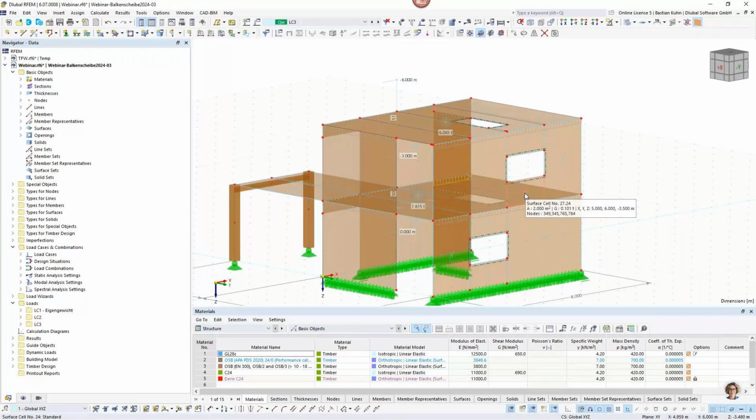Now that we are generating such a real nice 3D object, it is not necessary anymore, because we are calculating according to Eurocode 9.4, method B. And especially if you're calculating according to American standards, they don't even know the simplified approach. They are always calculating without dividing such elements. They are always using the more advanced design, I would say.